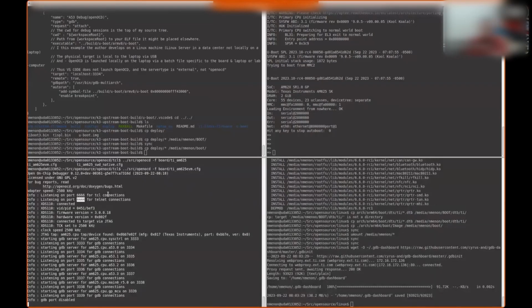Anyway, so the TCL option is also available where you can, for example, we had the GDB scripts, right, with CCS. You have a network port here through which you can send automated TCL scripting. You can actually map this up with auto expect as well. There's something called expect scripting, which is interactive. So you could literally write if conditions and a lot of other stuff that you could do with the TCL connection too. So there are so many different options with OpenOCD that you can do, literally.